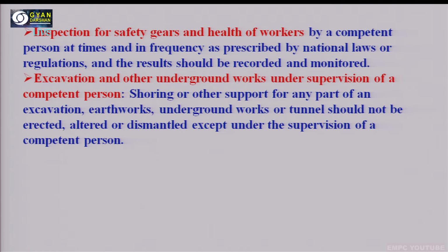Then inspection for safety gears and health of workers. This is also very important, because if some workers who are not fit for doing such type of work are working, then certainly some accident is bound to happen there. So proper health checkup of the workers should be done at the site before they go to that particular work. Second thing is that even those workers who are healthy should wear the safety gears.